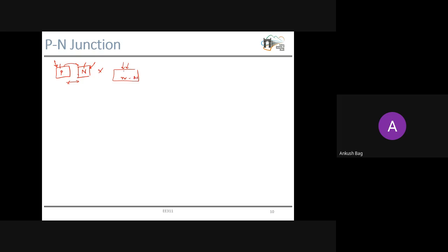This process is called implanting, typical to the silicon fabrication process. Implanting means high energy boron or aluminum or gallium atoms are bombarded from the top side, and they go inside this n-type semiconductor, and electrically the top behavior changes to p-type.